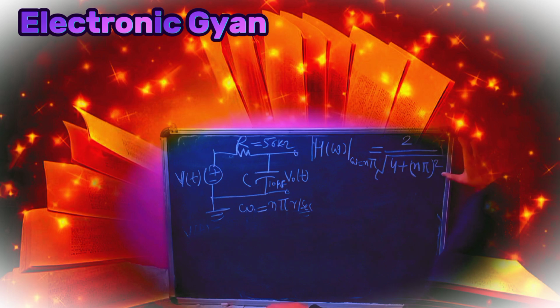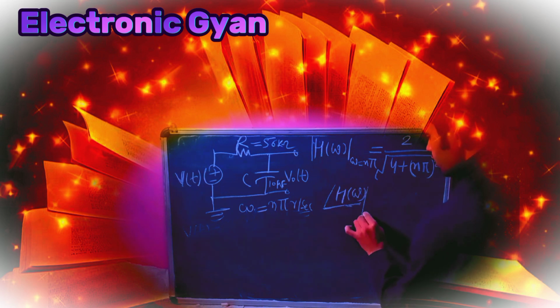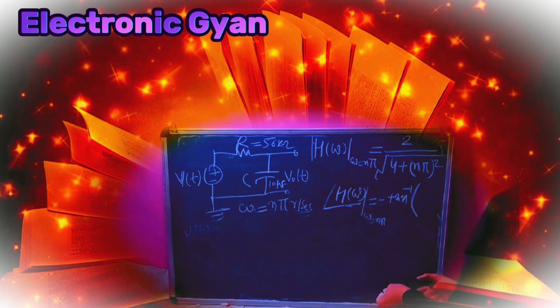So this is my magnitude response at the given input frequency, and the phase response for the given low pass filter at the given input frequency is what? Angle H(omega) at omega equal to n pi will be equal to minus tan inverse of omega by 2, that is, minus tan inverse of n pi by 2. So this is my phase response and magnitude response at the given input frequency.